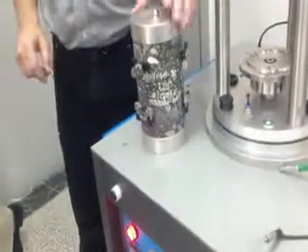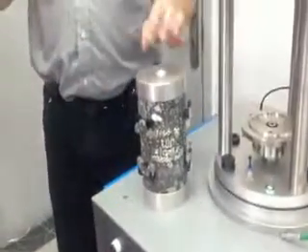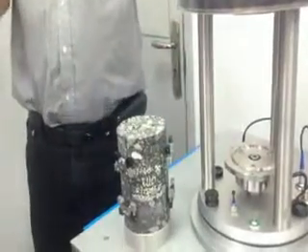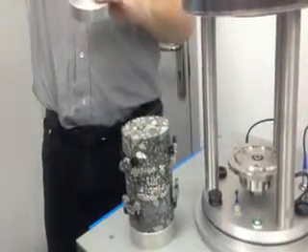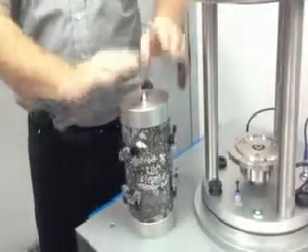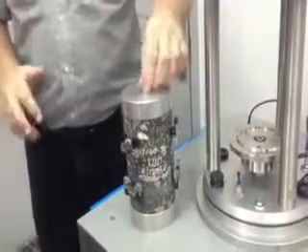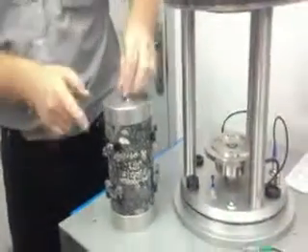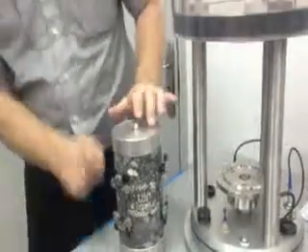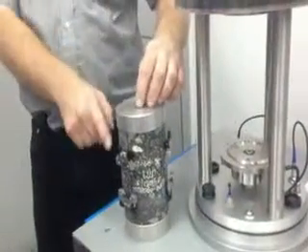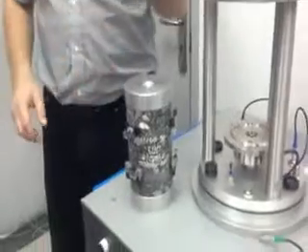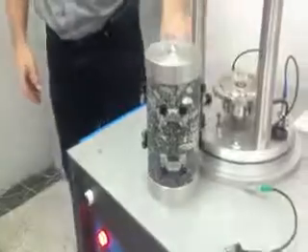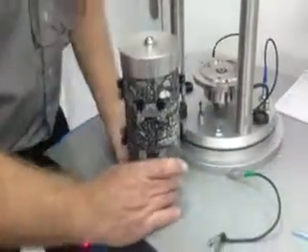On the top button, in the dynamic modulus test, they recommend putting a ball on the top. If your sample is not perfectly flat, this ball here will give you alignment. If you don't have this in, it's assuming that you've got a very flat, smooth sample. So normally for dynamic modulus testing, they use this. In the flow number test, they take this out. So from here, you can put the sample in quite simply.